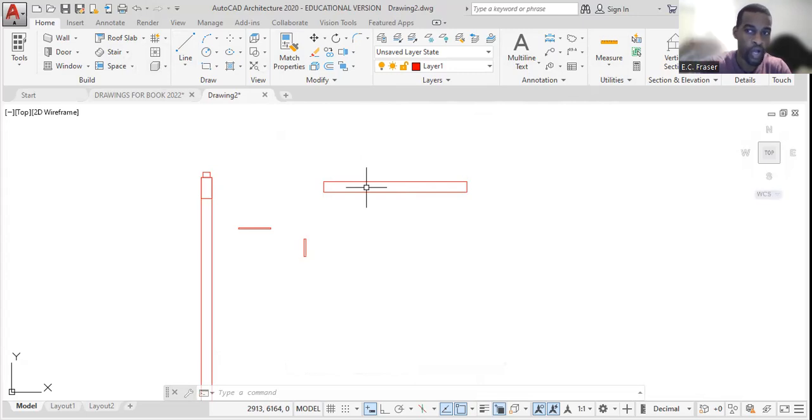Above the plyboard is the underlay. Above the underlay we have the roof material, which can be shingle, zinc, tile, or some other roofing material. This rafter should be inclined at an angle of 30 degrees in this case, as I want my pitch to be 30 degrees.